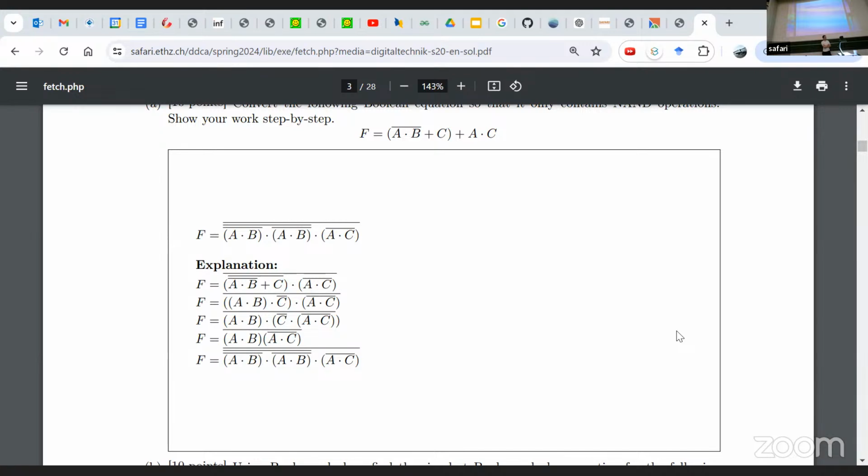You're talking about the load word instruction, which is from the ISA. How it is implemented depends on the microarchitecture. So in a single cycle processor, you have the address, you have the instruction, you construct the address, and you read from the memory combinationally. The data comes out, and at the end of the cycle, you write it back to the register. But this only happens on the next cycle, right? Like every other operation. R-type operations also work that way.